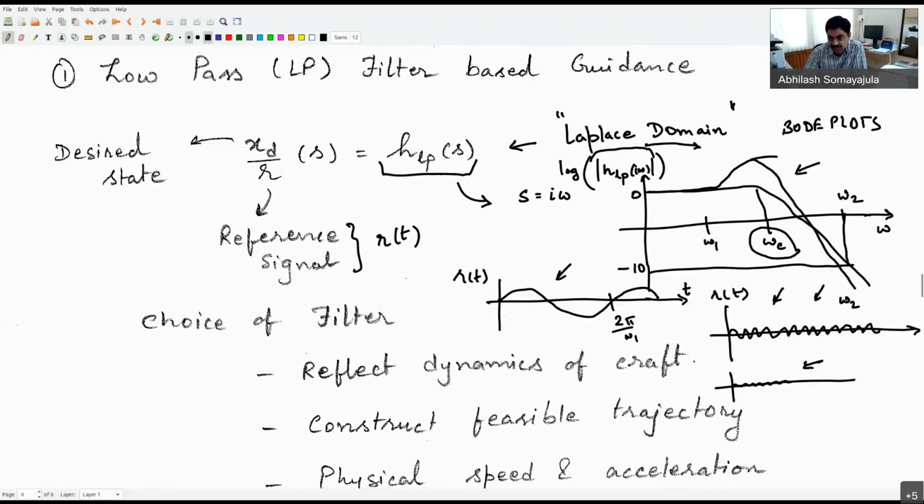So how large this overshoot value is will also be something that you as a designer of a control system or a guidance system will be interested to control. You don't want to see too much of it come into the picture. If the hump is too high, that means there is a significant resonance occurring. There is very little damping in the system, which may cause more problems.